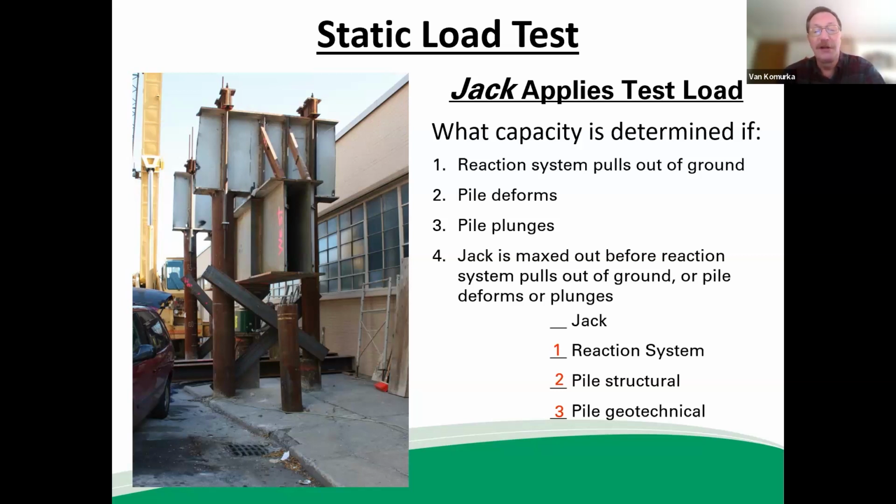Well, I just gave the answer away. The jack is maxed out before the reaction system pulls out of the ground, or before the pile deforms, or before the pile plunges. What you've done in that case is determine the capacity of the jack. That's all you've done in maxing out the jack, having it reach its limit, because the pile isn't moving. The pile still has resistance that the jack hasn't been able to mobilize. So all you're evidencing is the jack capacity. Okay, that seems simple and straightforward.